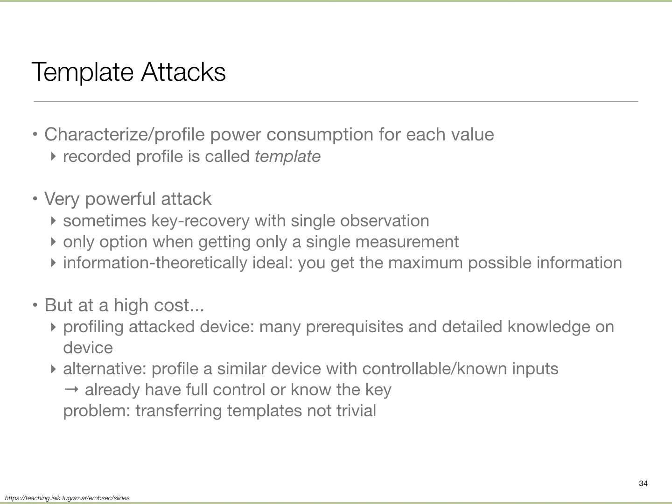Firstly, I need access to a similar device to the one I'm trying to attack, and then be able to collect and build up this profile. So if I have a device whose code I know and which I fully control, I can operate it under different input conditions, collect the traces, build up a library, and then work it backwards.